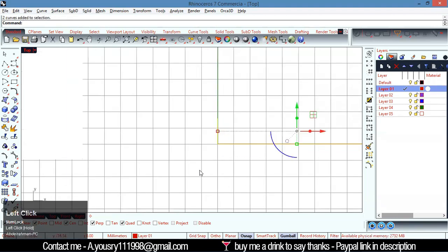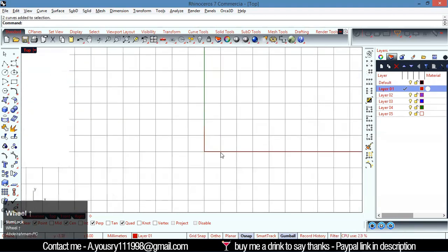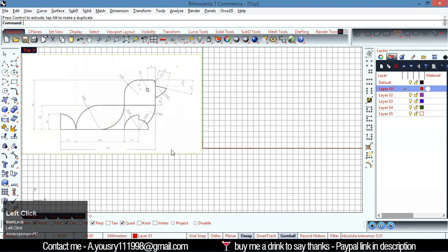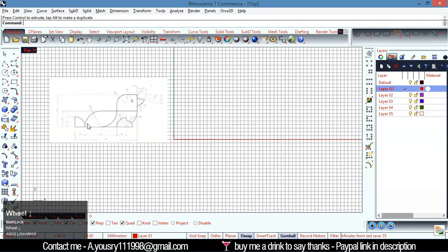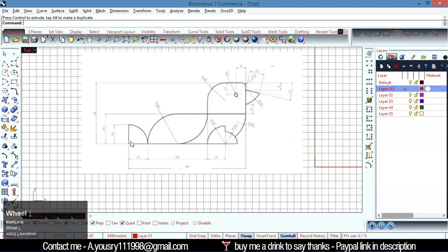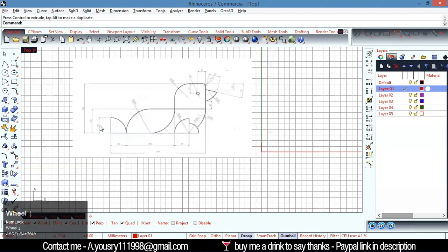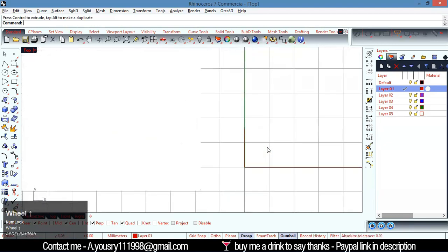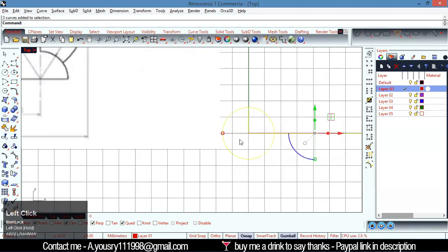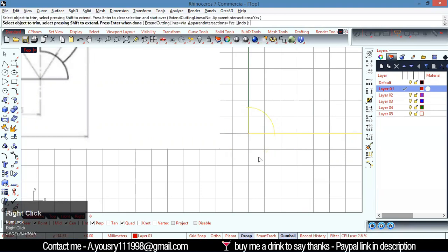I just changed that to another color so you can see it clearly. Okay. After that, I have a circle here which is 16 and 16, so its radius is 16. So I'm going to hit circle, enter from here and also here. So let's pick these, Control T to trim.